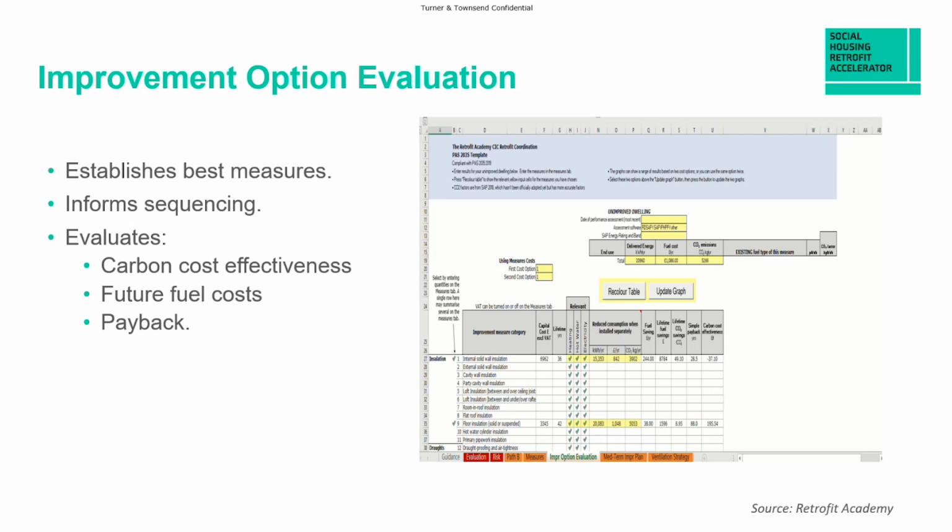You need to consider more than one approach. One of the other things you can look at is future fuel costs. Obviously, that can only be calculated on the current price of energy, and it will change if energy costs change. So you just need to understand that. And then you can do a payback calculation. So this is to look at how quickly you are going to be able to pay off the cost of doing that installation through bill savings.